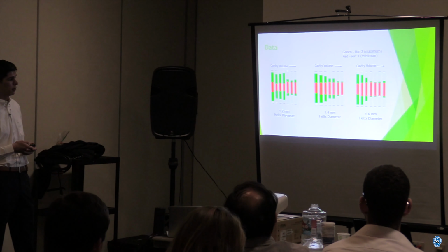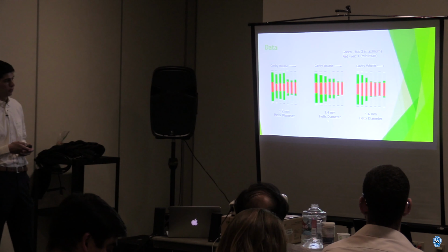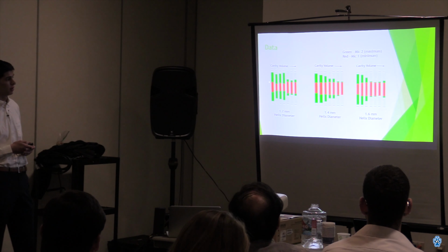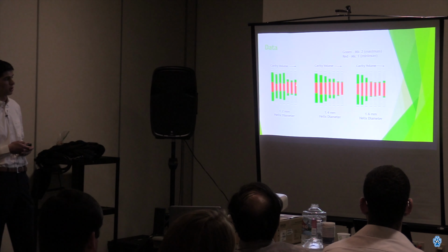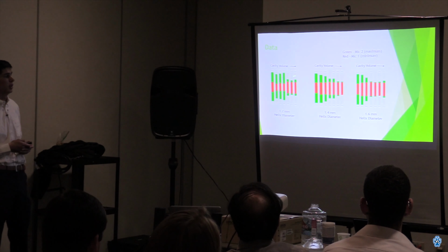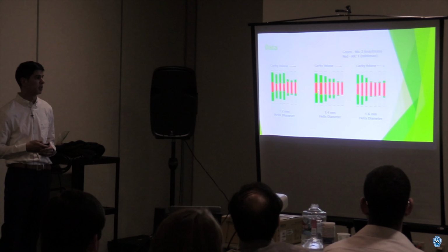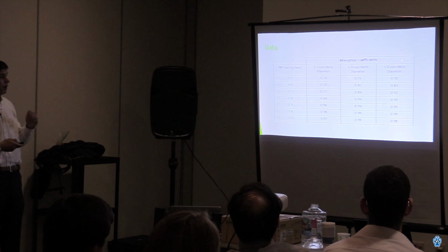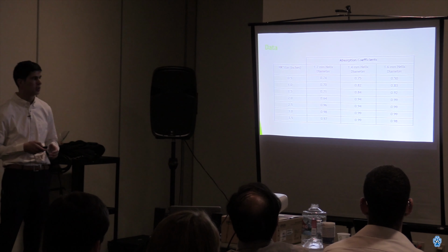So I have three separate samples: 1.2 millimeter, 1.4 millimeter, and 1.6 millimeter. And this is just the increasing cavity depth. The first one starts at 0.5 inches and goes all the way to 3.5 inches. So I'm easily able to calculate the standing wave ratio from this information, and from here, I was able to calculate the absorption coefficients.